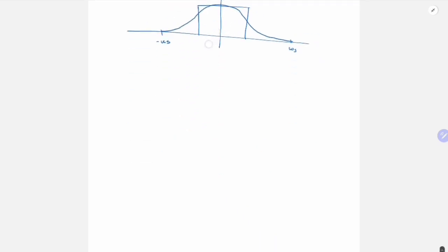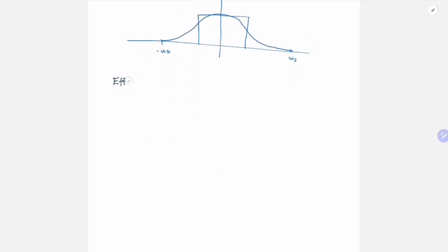So next we'll quickly see the effect of undersampling. It is also called aliasing. So everything is fine if we sample omega s greater than 2 omega. It's good. But what happens when omega s is less than 2 omega? Let us try to understand that. For that, we'll take a simple example, cos of omega naught t. So let's say my x of t is cos of omega naught t, and at first let's say my omega s is 2 omega naught or 3 omega naught.